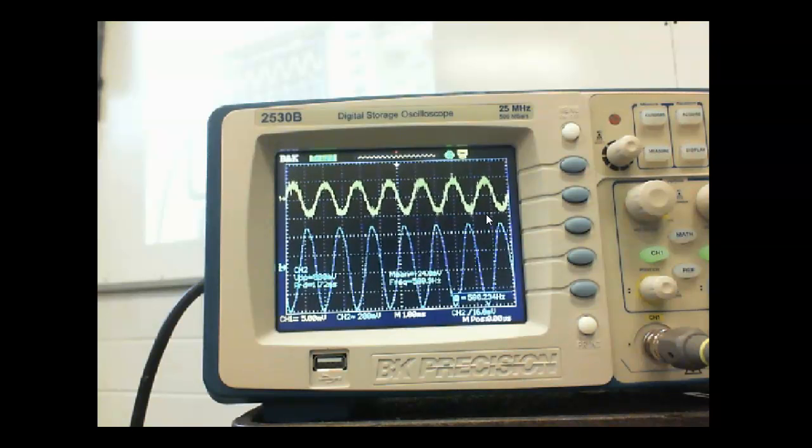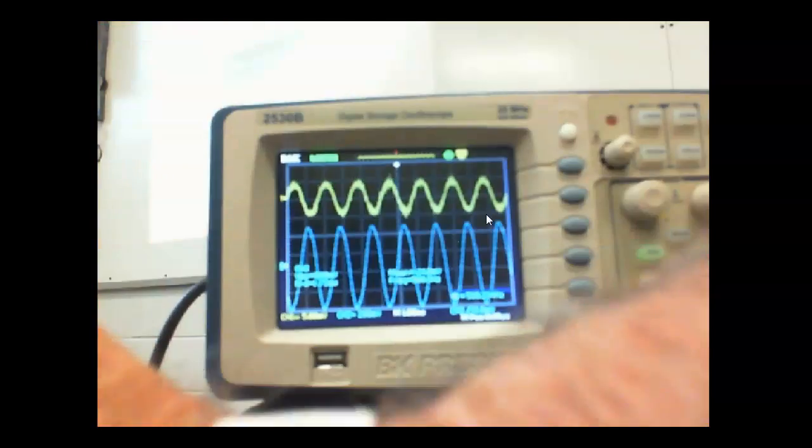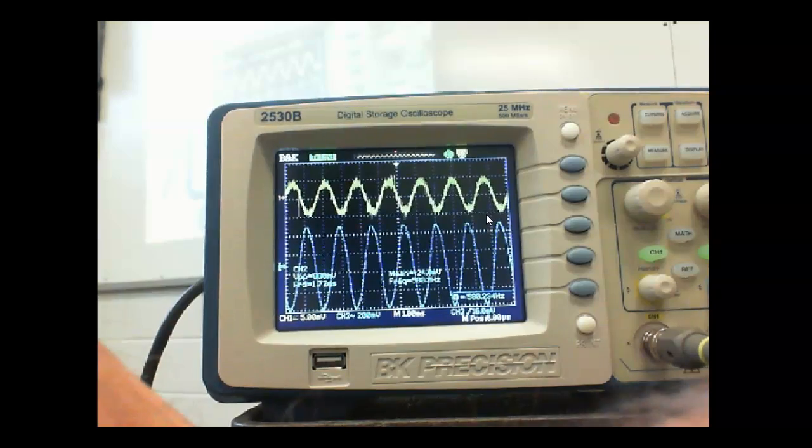Because right now, that 6.8K is only dropping the current required by IE, right? You understand that? So here we go. We're going to put this guy in here. Here's my 10K. I'm going to put it in parallel with my, what's our output? 6.8K collector.